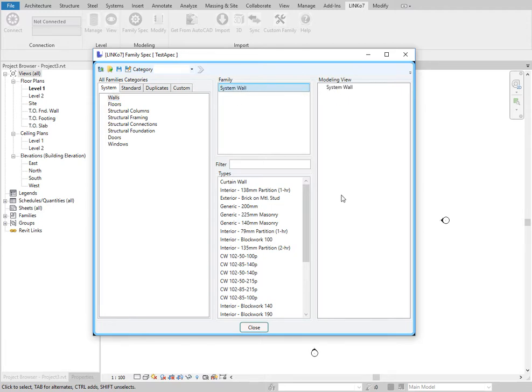So this is like a tree view. You can add elements here, and this will go on to any level you want. So you can say, okay, system walls, and you will drag and drop this under here, so it will go here. Keep adding, and you can see this is all metric. So depending on the template you're loading in AutoCAD and REVIT, you will get the specific elements.